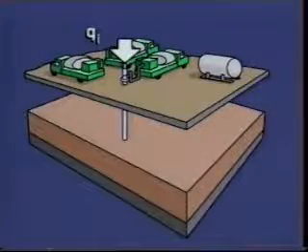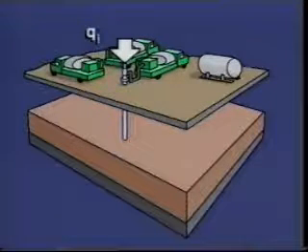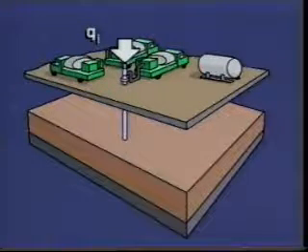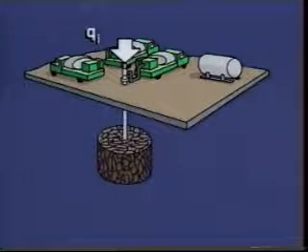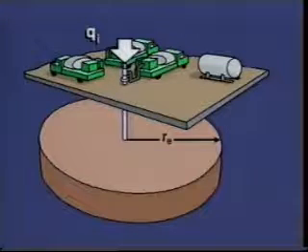The injection rate at which the HCl pre-flush and HF acid will be pumped into the formation depends on the type and extent of formation damage. We can estimate the injection rate for a damaged well based on the skin factor calculated from the pressure transient analysis. To do this, we must first calculate the injection rate for the undamaged zone.